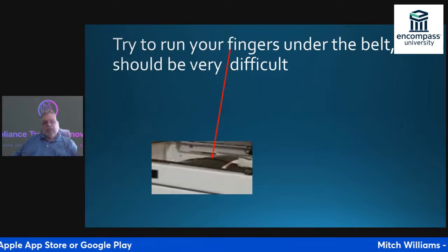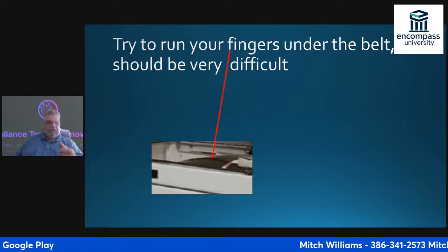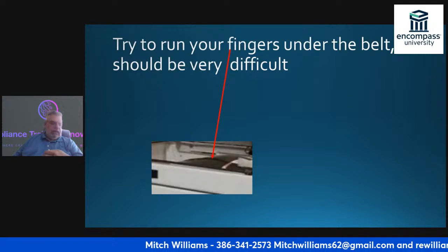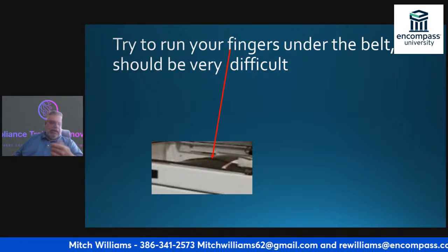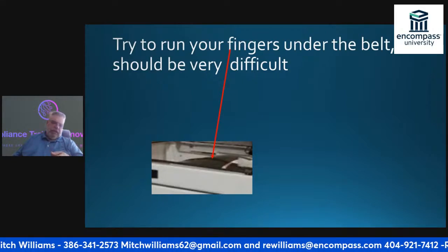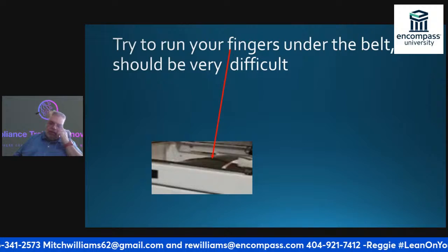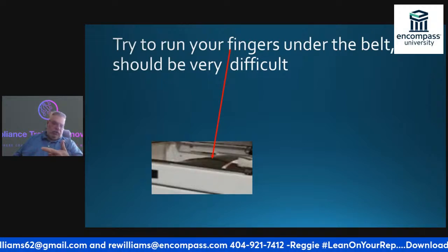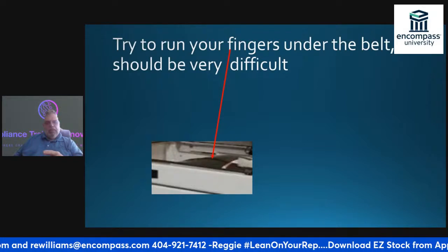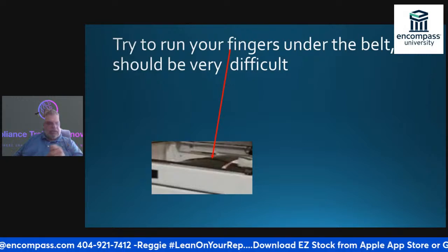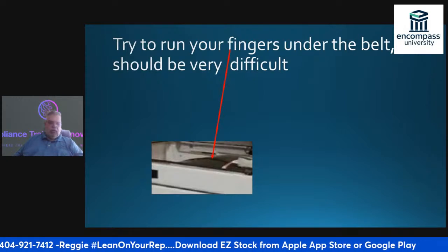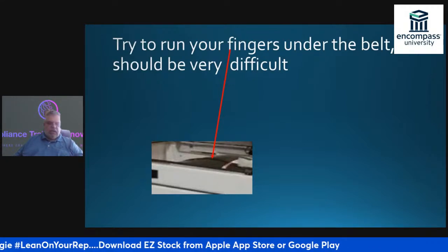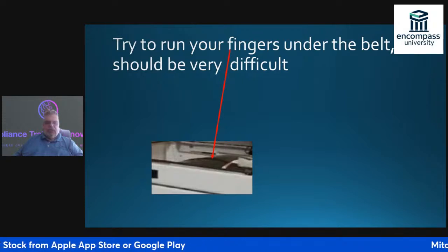I'm going to take those 2 5/16 screws out. The switch has a little clip that runs across the front of it. I'm gonna undo that clip. I'm gonna put all 3 pieces into a container so that I know which screws these go to.